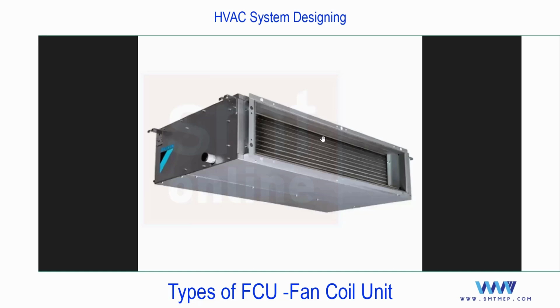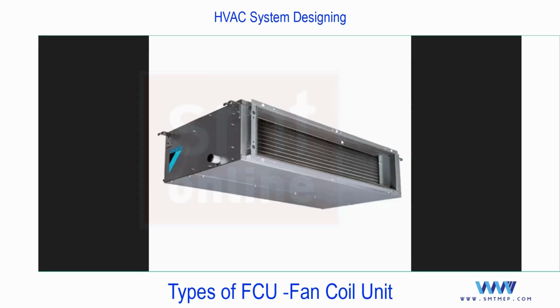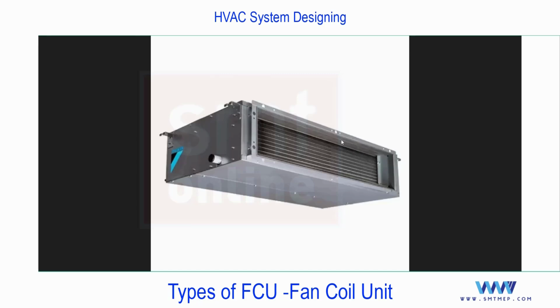And this is a supply mouth, and you'll find a piece of a duct which will run up to the gypsum board, the false ceiling. And on the gypsum board, you'll find a grill. At the time of air side, I'll show you more detail about the grills or the air terminals. At this level, just try to understand the different types. So this is a horizontal conceal FCU.